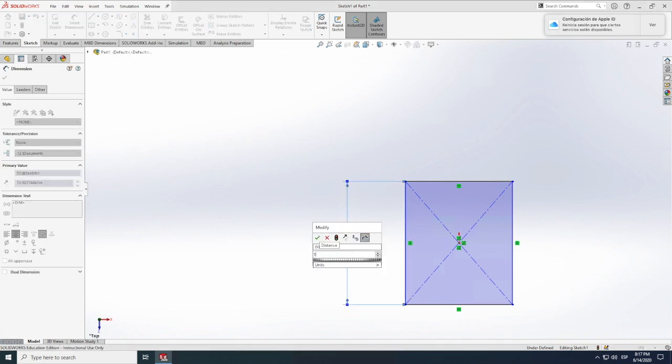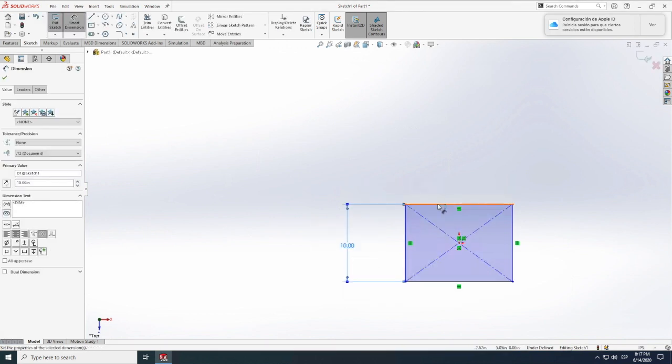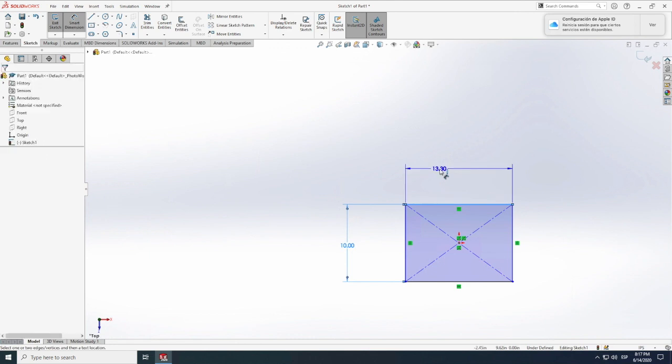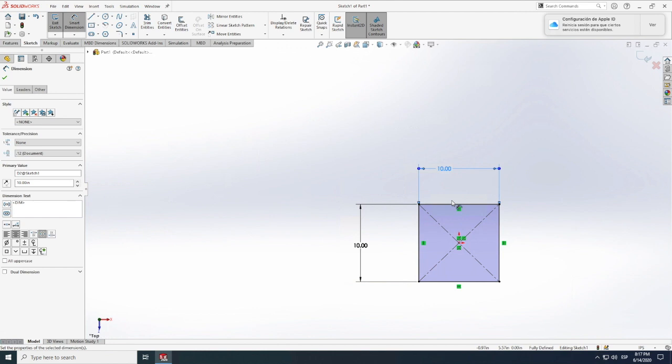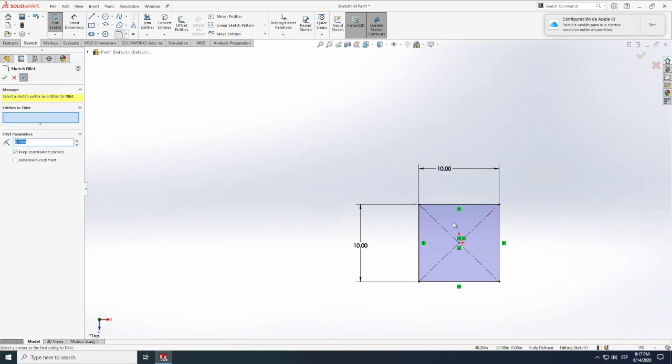And I should say that there are so many different ways of doing whatever you need to do in Solidworks. By no means is what I'll show you in these videos the only way, but it's just a way, if it makes you feel better. So if we go here to sketch fillet, let's click in there and I'll show you. You can choose one point like that one, and let's choose those 2 points. And then if you see it over there, what we can do is just specify a radius, right? So let's go here for 0.5. Let's see what that does.